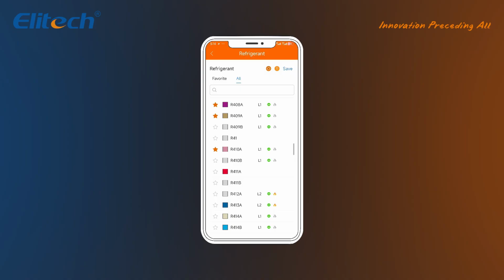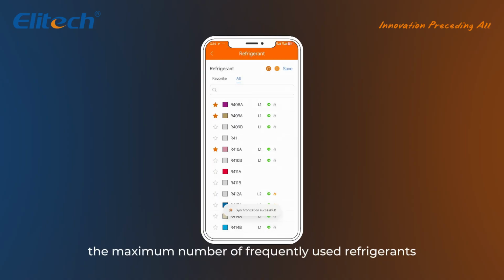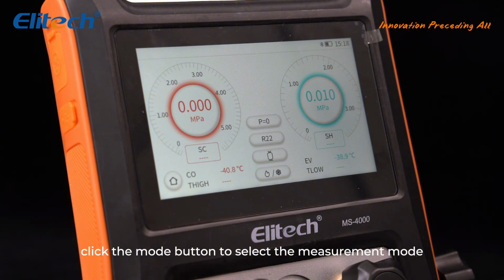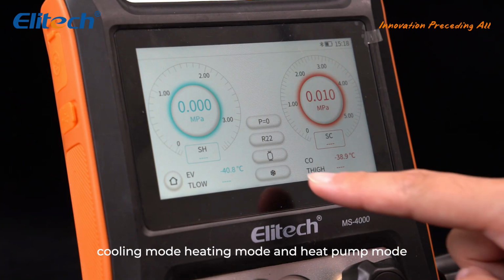After selection, click frequently used, and then click the update icon. The maximum number of frequently used refrigerants that can be added is 20. Click the mode button to select the measurement mode. There are 3 measurement modes: cooling mode, heating mode, and heat pump mode.